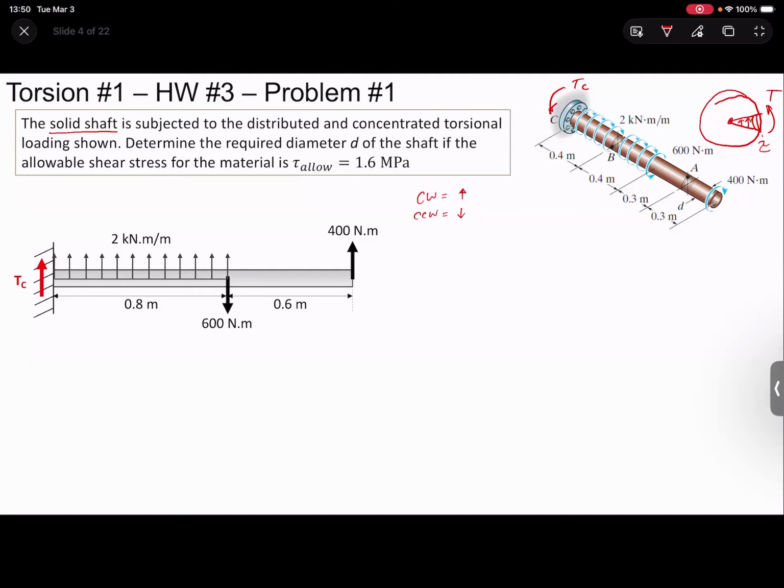So we need to set a support reaction, and we're just going to say it has this clockwise. So sorry, to be consistent, let's say it has a support reaction that way. Now, when we view it this way, we can set up our statics equation. It looks like the summation of forces in the y direction, but it's really the summation of torques at C equal to 0.